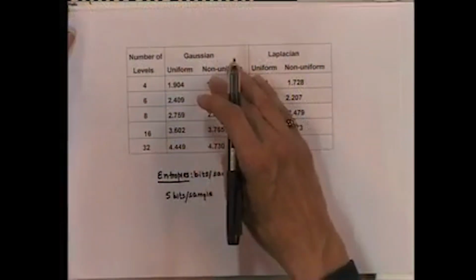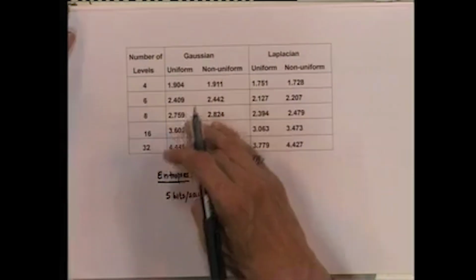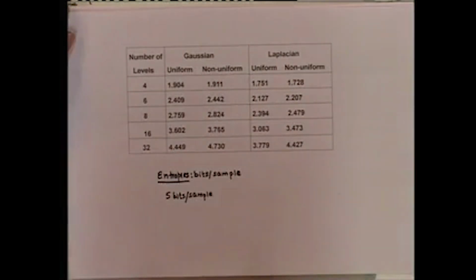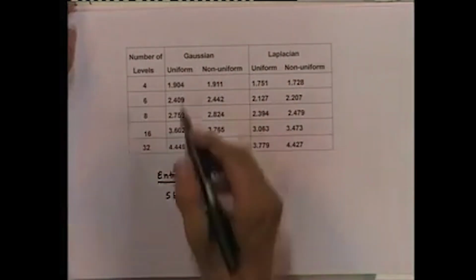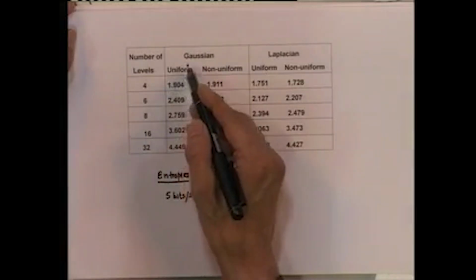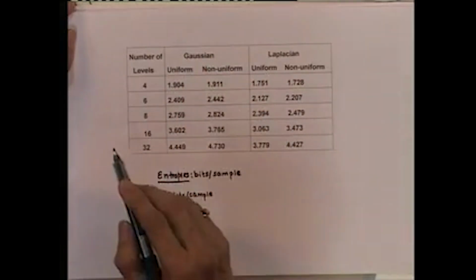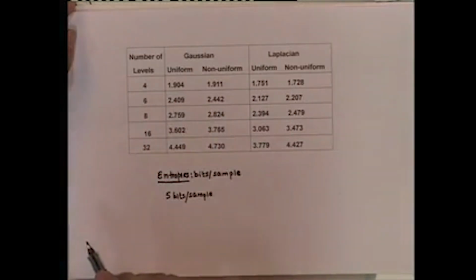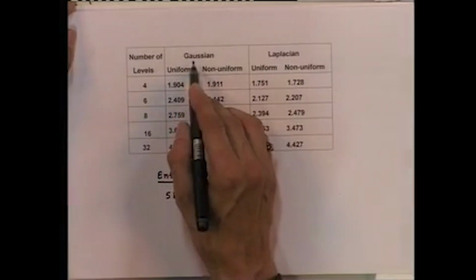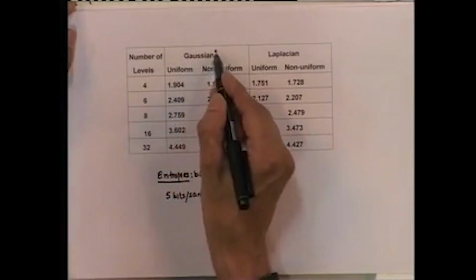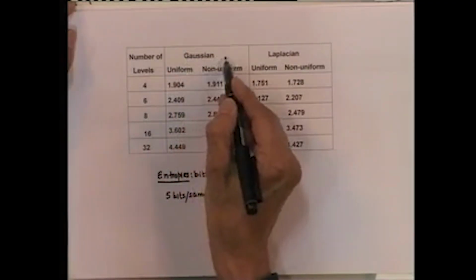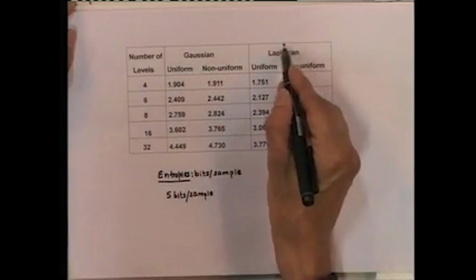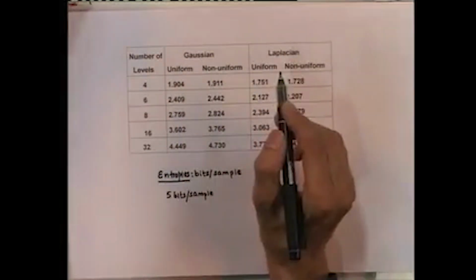And because of this, the output entropy of the non-uniform quantizer is higher with respect to the uniform quantizer. Another observation is that closer the PDF is to being uniform, the less difference in these rates. Therefore, it is observed that the difference in rate is much less for the quantizer for the Gaussian source than the quantizer for the source having Laplacian PDF.